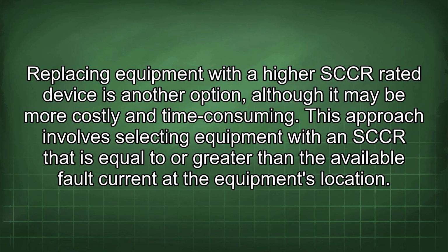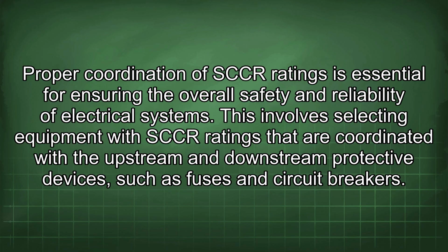Replacing equipment with a higher SCCR-rated device is another option, although it may be more costly and time-consuming. This approach involves selecting equipment with an SCCR that is equal to or greater than the available fault current at the equipment's location. Proper coordination of SCCR ratings is essential for ensuring the overall safety and reliability of electrical systems.